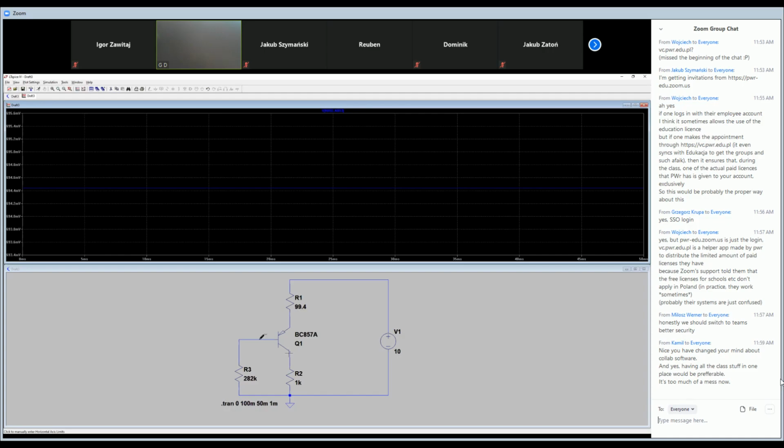And as we have LTspice running at this moment, I can show you what happened when we plug in the input signal. First of all, we have to put capacitors here, because DC current cannot pass through to the generator or to the load resistance.